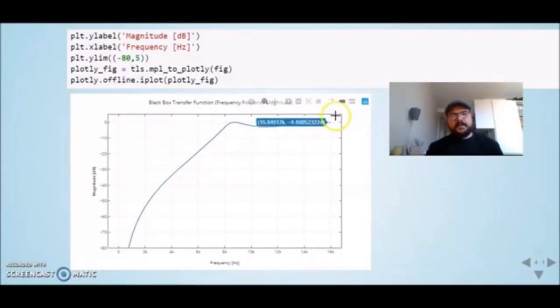By analyzing here, we see these ripples in the pass band. It looks like a high pass, cutting until around 8 kilohertz. It has these ripples, and at 800 hertz it's already at minus 80, minus 78. We see there is a roll-off that is more than 60 dB, but less than 80 dB. Perhaps this would indicate that it's a third order filter.